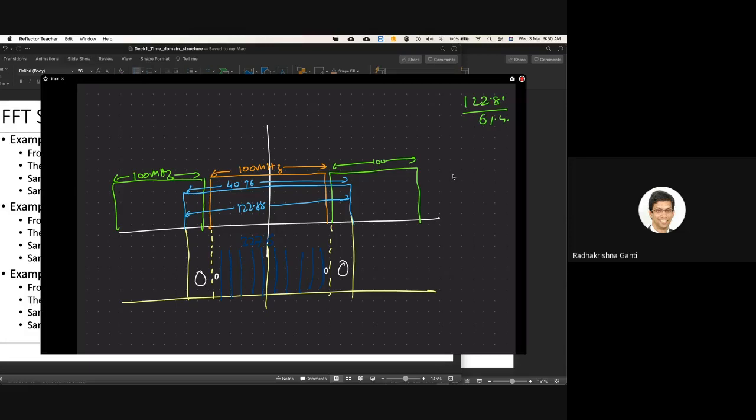So effectively, how will your spectrum look if you draw it? Because you're putting zeros here, nothing is going to come out in those frequency bands. So your effective spectrum will look like this. It is still 100 megahertz, or a little bit less than 100 megahertz.